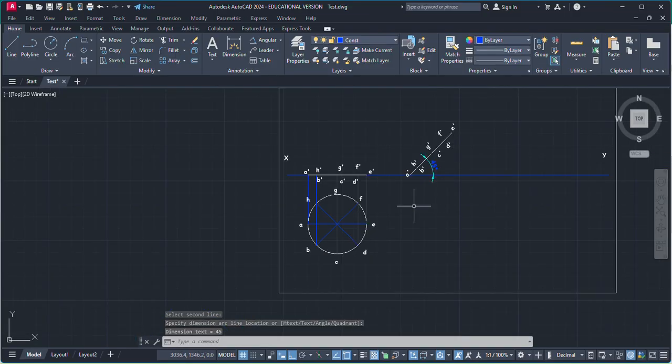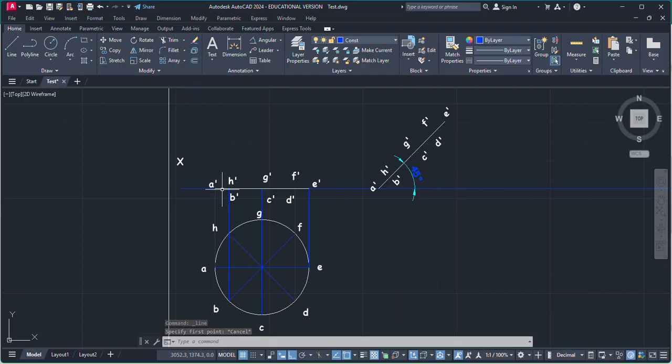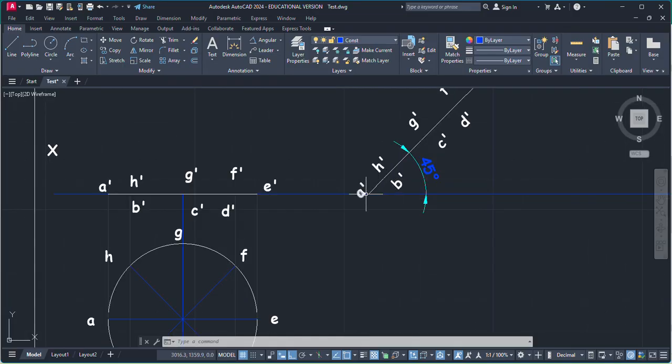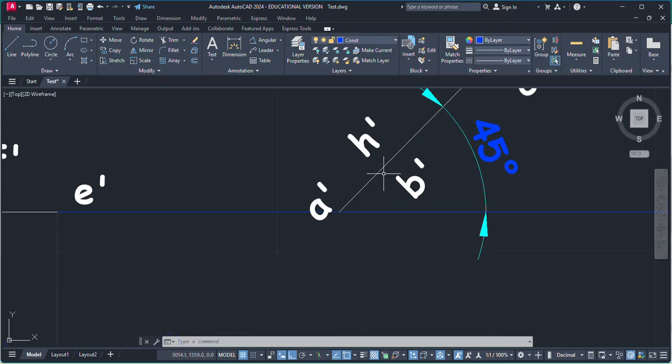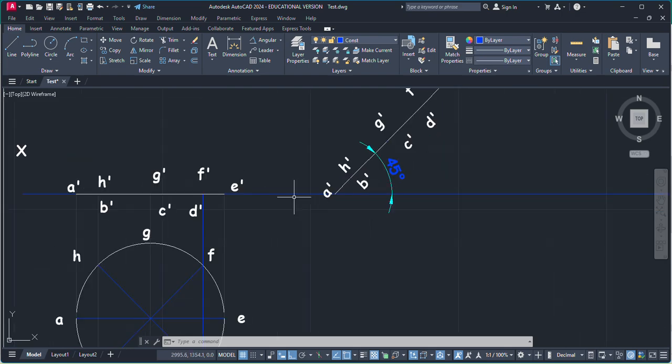So now from this front view, when this surface gets inclined at 45 degrees with HP, in front view we will have the inclined line. Now from this inclined line we have to trace out our top view. Previously I told you I've created this front view in multiple segments: this one, segment 1, 2, 3, 4. This is done because if I had created a single line from here to here, it would be very difficult to trace out that S dash B dash point with an accurate length. That is why I've created this front view in multiple segments.